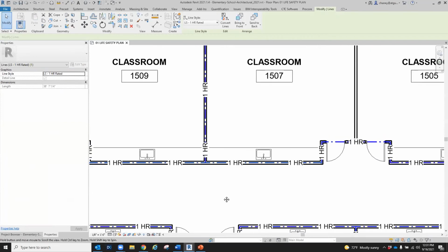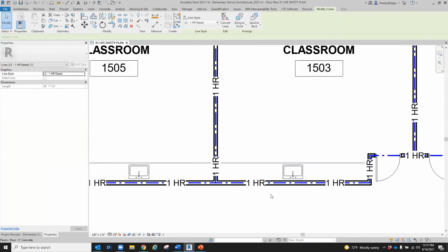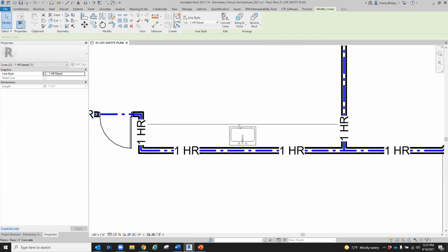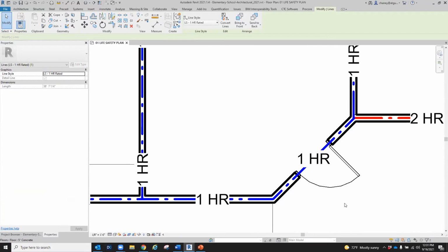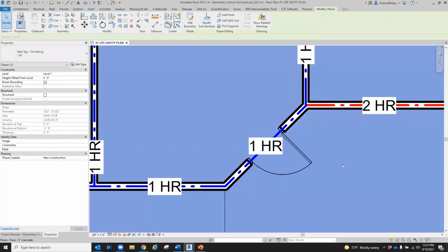Blue with tags every 10 feet, minimum of 2 feet off the connections. And you can see it's mostly oriented to the wall. So as I was saying with those angled walls, it's going to show vertical or horizontal because a tag can only be vertical or horizontal.